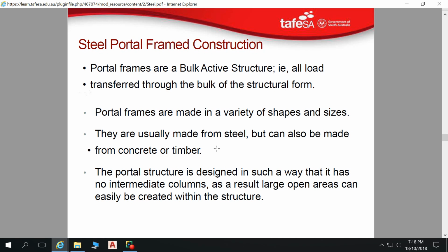But one building which I found really surprising in how well it stood up to that fire was a building adjacent that oil facility. Now, I guess it all depends on where the oil was and where it was burning as to the intensity of the fire and which way the wind was pushing it as well. But there was this building next to that, which was actually a timber portal frame building. Well, it was a plywood portal frame. So they had these huge, thick sections of plywood making these portal frames, so engineered timber, then with wall girts on that, and then steel sheeting on the outside.